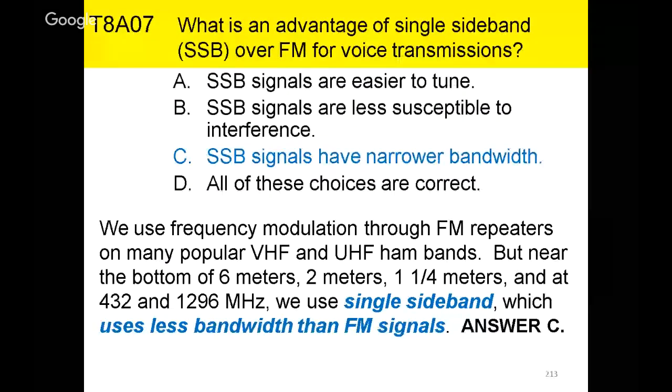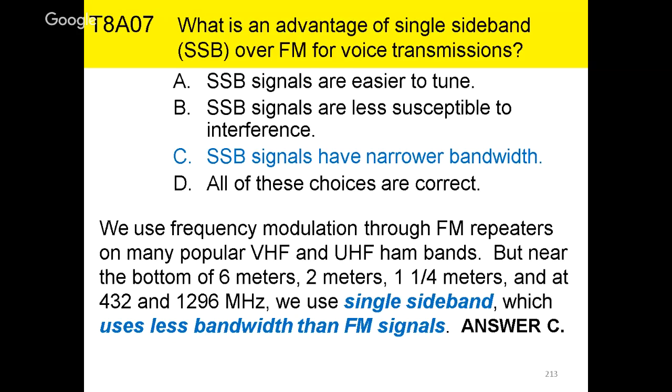A typical AM transmission, which contains your carrier frequency as well as the upper and lower sideband portions of the modulated signal, is approximately 5 to 6 kilohertz in width total, versus the FM, which is much wider, typically 10 to 15. And then your single sideband of that signal is even less than the AM. So it's like half of the AM signal.